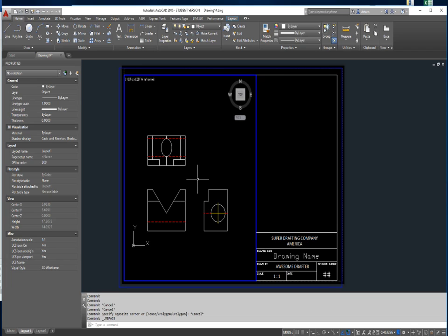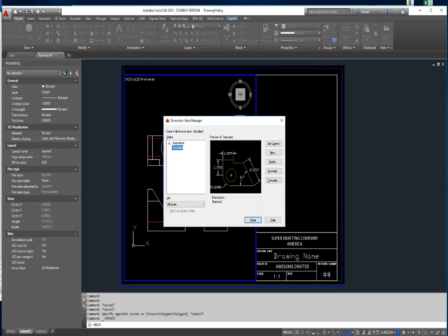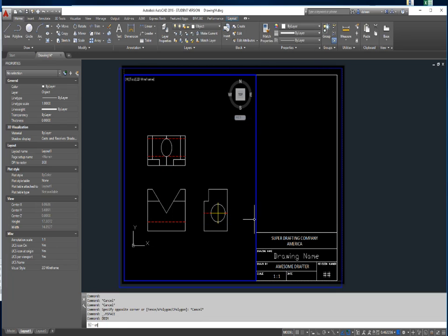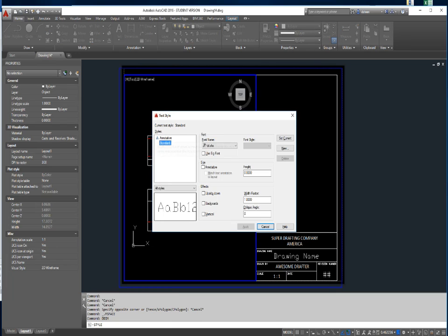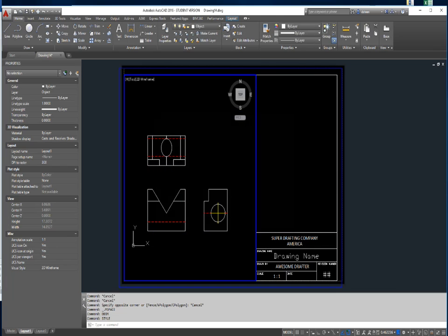So what can I do with this? Well, if you come down here, you get some icons that look like the side of a little scale. So I'm in AutoCAD and I want to create an annotative dimension style. You can see there's this little blue icon that looks like the side of one of the scales you were issued in class. And if I do style, if I was going to create a new text style, there's an annotative text style that you can create. Well, down here, right there, I get some different scales.